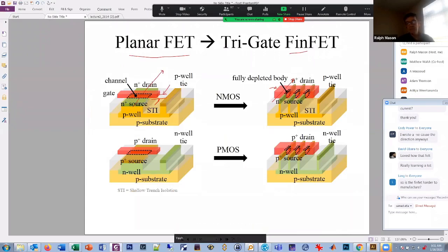So that's the newest technology, it uses these FinFETs. And one of the things that came about, I already mentioned, is that now the PMOS and NMOS, they were able to adjust them so that basically the mobility of holes and electrons is the same. And it kind of relates to the strain that's put in these devices.